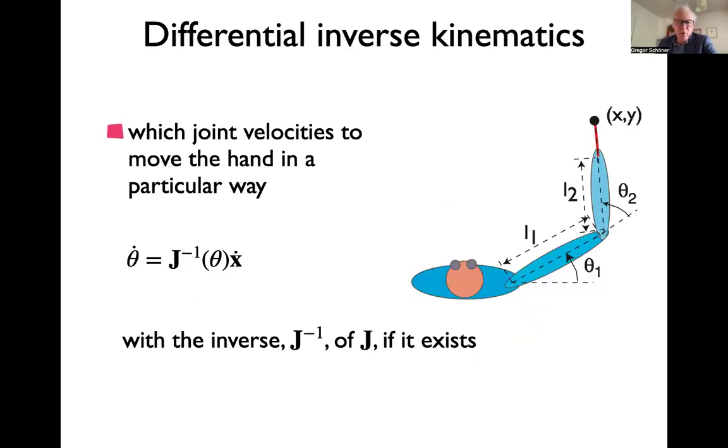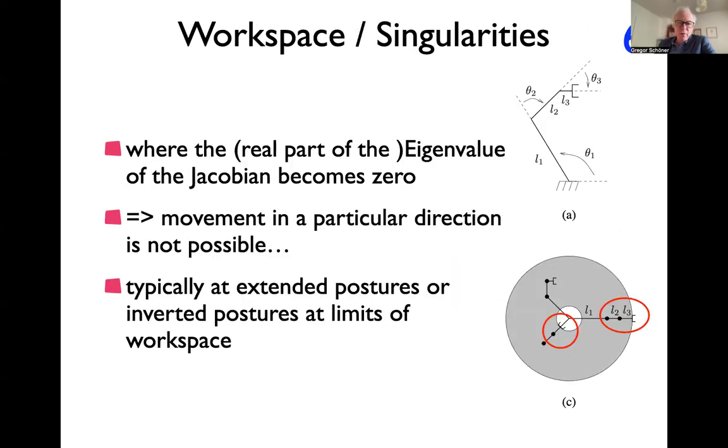The other problem in inverse kinematics is the singularities, that there are points where this inverse fails to exist or becomes very unstable. So it becomes very sensitive, and that's typically at the joint limits. If you stretch your arm out this way, or you can also stretch it by rotating inside, then you reach positions where in one direction you can no longer actually move, and it will make the end effector position become a sensitive function of some joint variables.